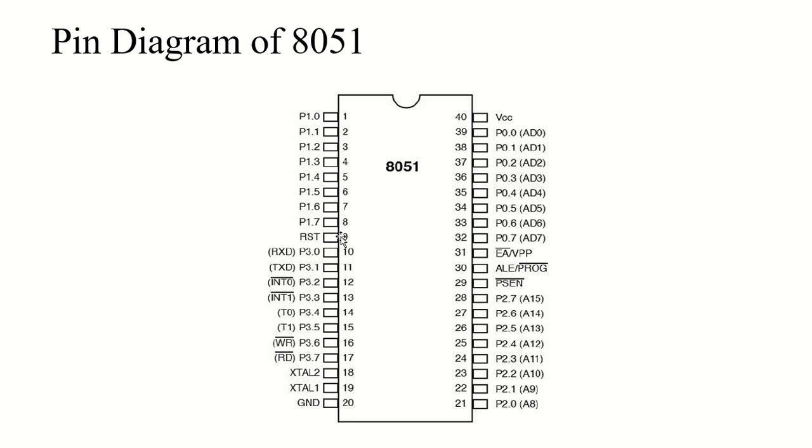Each uses 8 pins, which makes them 8-bit ports, and all the ports upon reset are configured as inputs, ready to be used as input ports. When a 0 is first written to a port, it becomes an output. In order to reconfigure it as an input, a 1 must be sent to that port. I'm telling you, remember this every single time you are dealing with the ports.